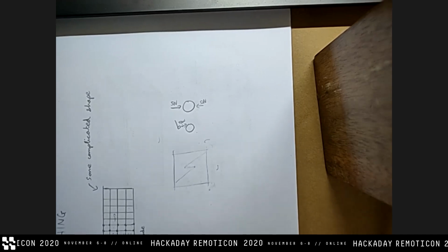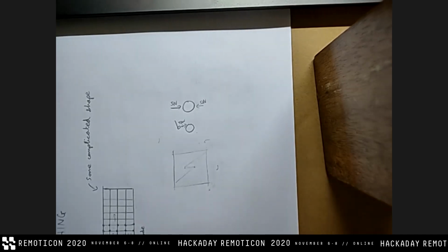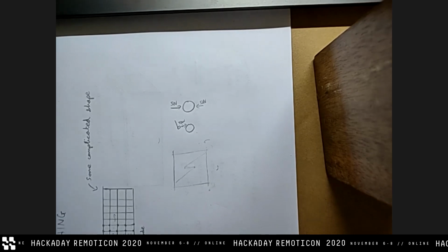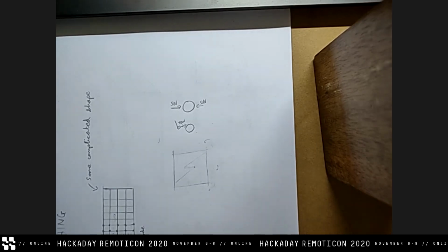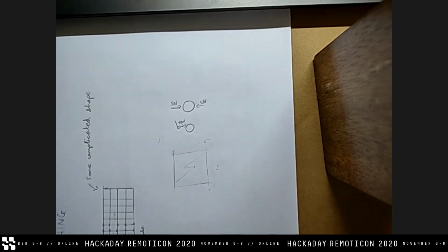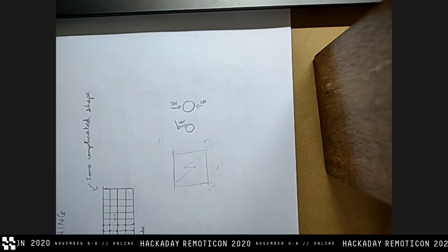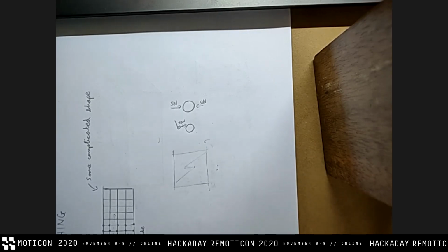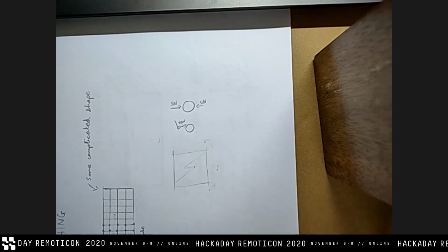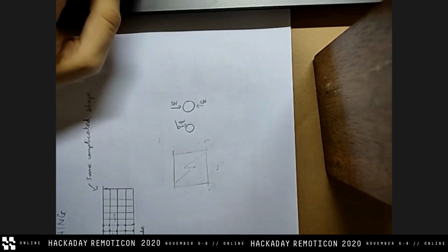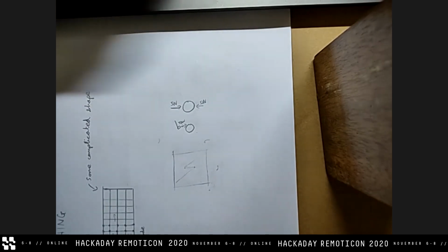Yeah, that's actually a really good question. I used STEP and I regretted it because it led to a lot of topology issues, and I tried to spend a day solving them, and then I found out that no, IGES is just better. So for most examples of simple geometry, STEP should be more than okay. But when you're dealing with more complicated geometry...